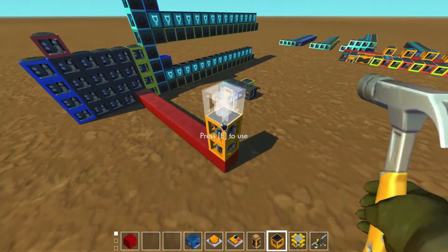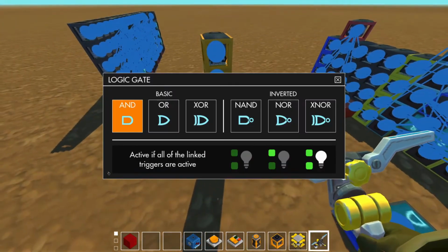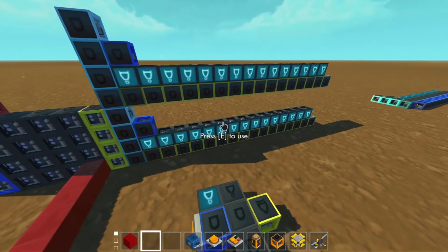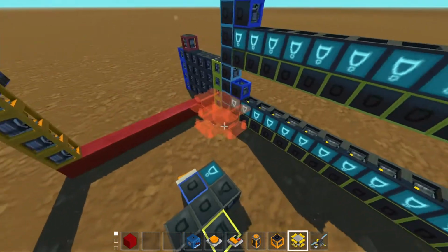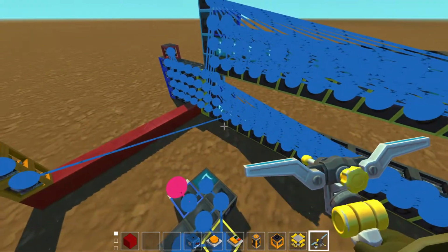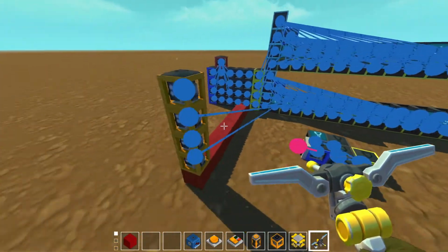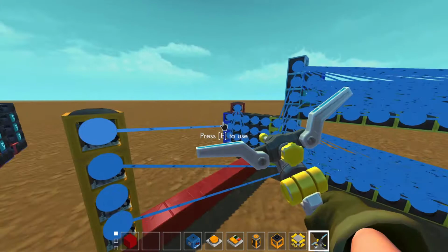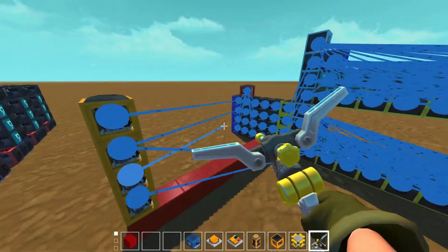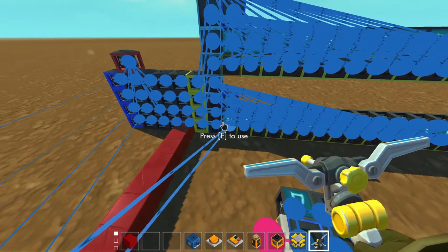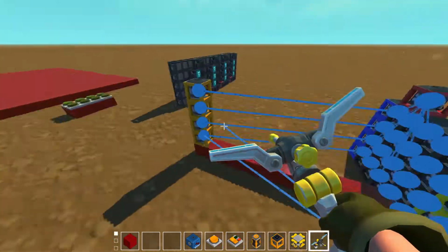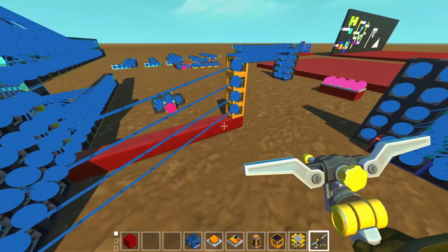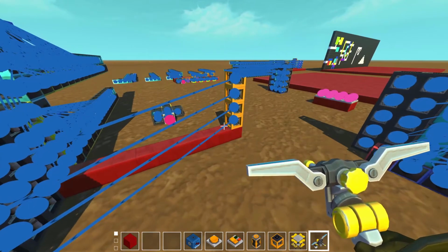So, one thing I can simply do is have each one of these out pins for these branchers or selectors have a specific combination of bits selected here, so that when they're active, it sends a single value, which can then be routed directly back into the state, which will allow us to alter our state conditionally based on whatever and decided by us. And so that will be the hard-coded instruction set of the machine.